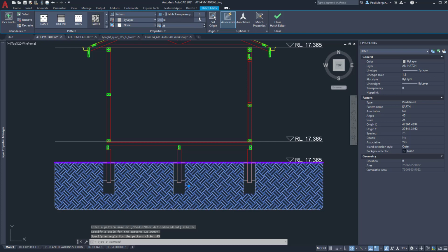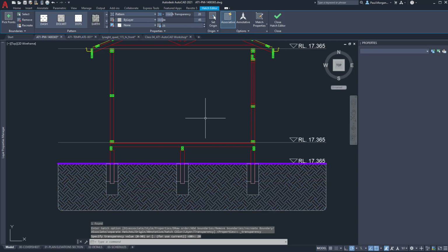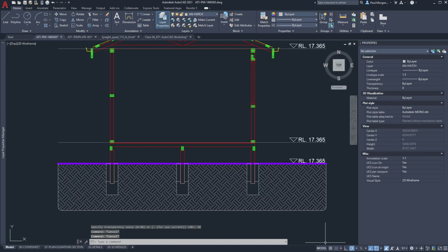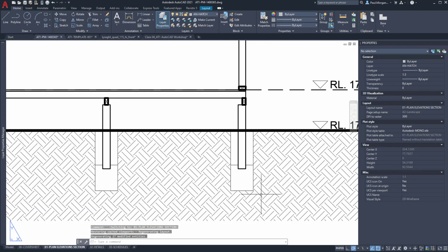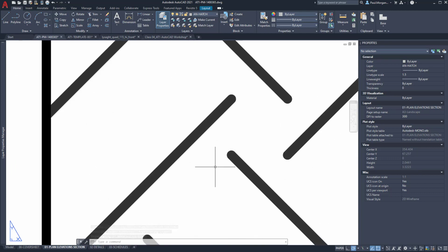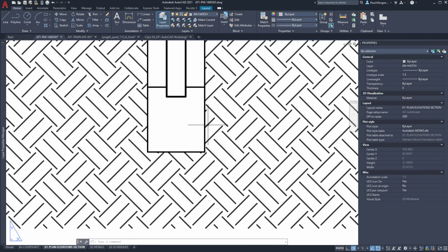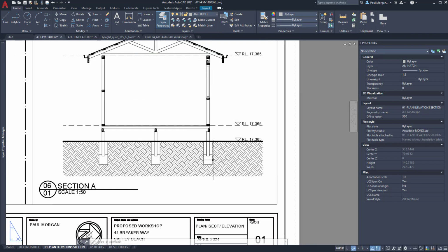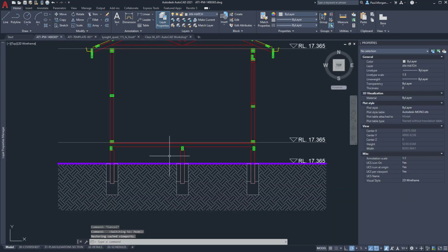And then also the hatch transparency, I might change that to say like 20% transparent, just so it's not like solid black lines. And then you can see what we've got here. I'm going to delete this outside line and then go back to our sheets, and you'll see there's that hatch pattern there. And because I've made it 20% transparent, when I zoom right in, notice the difference between this line that's fully black and this one's like a dark gray. I know it doesn't seem like a lot, but when you do print it, it will just appear much more pleasing to the eye. All right, let's keep going with that.